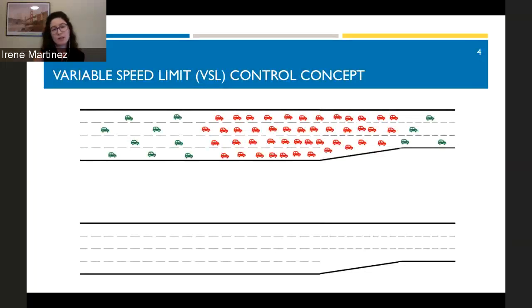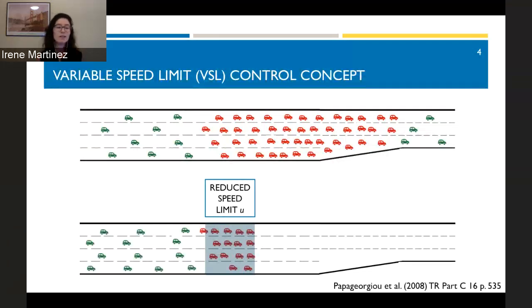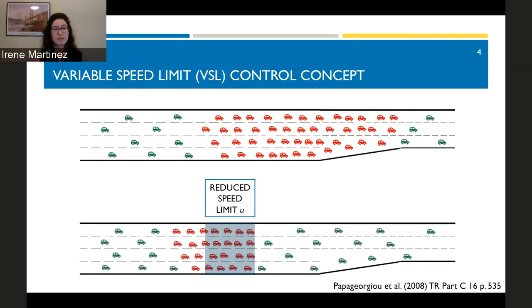You have presumably an excess of demand that would generate a very severe queue. What we do is to generate an upstream region with a lower speed, which reduces the flow into the bottleneck. This artificial queue is supposed to let vehicles accelerate away from this zone and pass through the bottleneck without stopping and without causing the capacity drop.